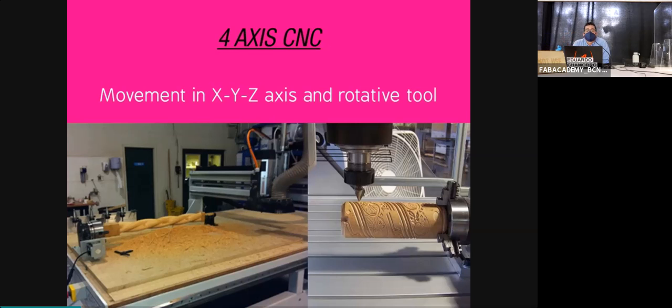It's funny, but this accessory is also sold for laser cutters. For example, a lot of glass containers are laser engraved. How do you engrave something cylindrical with a laser cutter? You need to rotate it to always keep the focus on the tool, so you rotate the bottle. It's funny because when you embed this accessory in a laser cutter, it's no longer a 2D laser cutter, it's a 3-axis laser cutter. It's not a 4, it's a 3.